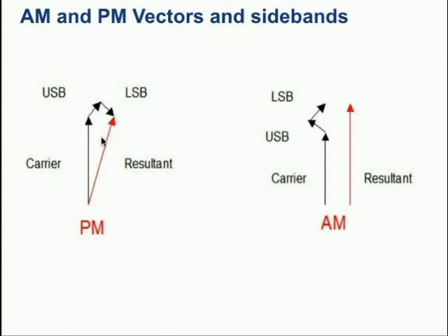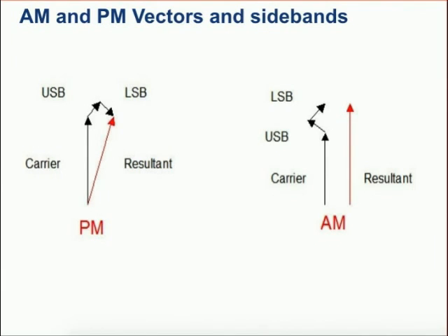Now, in the flicker region it's more complicated, but when we're just talking about broadband white noise, then really this phase modulation of the carrier can be seen as additional noise sidebands that add to the noise figure of the device. The measurement of the noise performance of a device with a high-level carrier going through it is known as an added noise measurement.